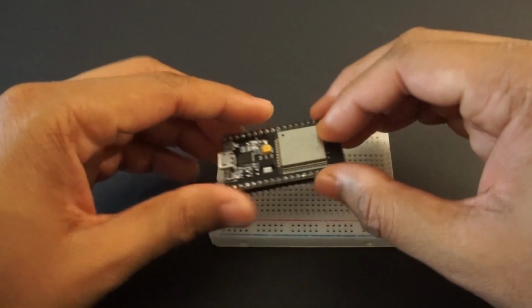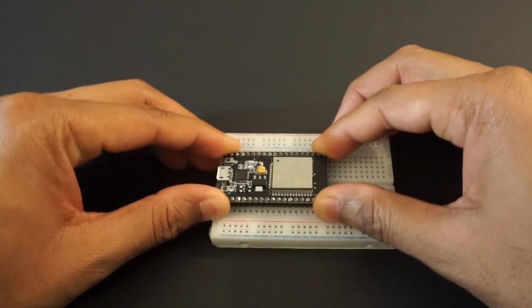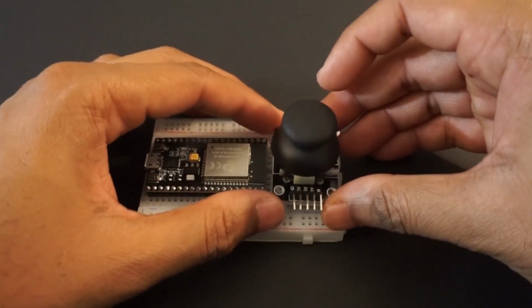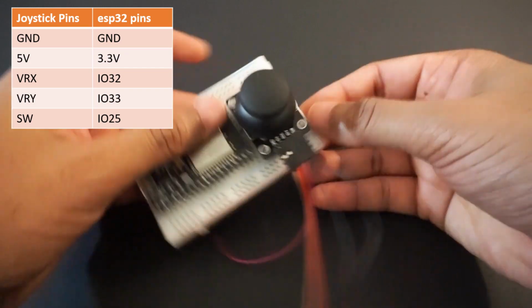First, mount the ESP32 board on the breadboard. Attach the joystick using double-sided tape on the breadboard. Connect the joystick to the ESP32 pins now.